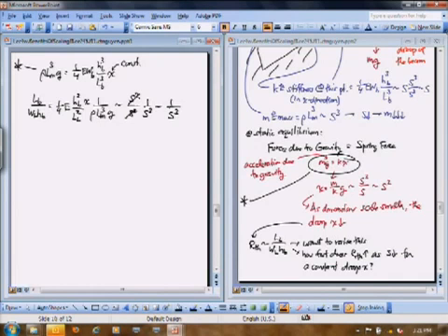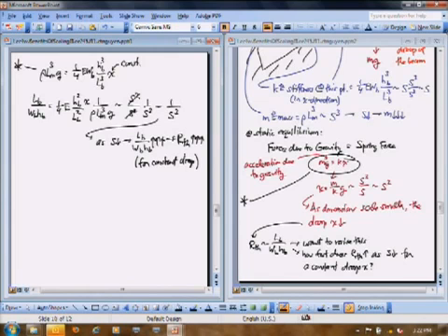That's the third power, which means that the thermal resistance goes up in a hurry for constant group. So that tells us what we've already figured out, that if we scale all the dimensions for anything supported by these long meandering struts, we can raise our thermal resistance. It is scaling that allowed us to raise our thermal resistance, that allowed us then to reduce the power that we put into this system to keep it at a steady state temperature. And because of the thermal capacitance scaling as well, it allows us to lower our thermal time constant.